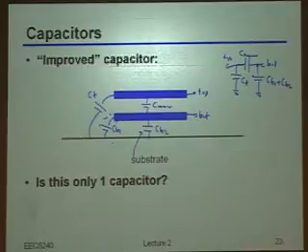So what you said was that, hey, well, in this picture, there's kind of a couple things that in principle I should be able to do, right? So one is, if I could increase that distance from the substrate to the bottom layer, I'd have less parasitics, right? The second thing you said was that if I could actually reduce the distance between those two capacitors, that would also be good for two reasons, right? One is it would pull me potentially farther away from the substrate. And second is, and more importantly maybe, it would actually increase the capacitance that I really wanted, right? That main capacitance would actually go up. So everything you said is in principle true.